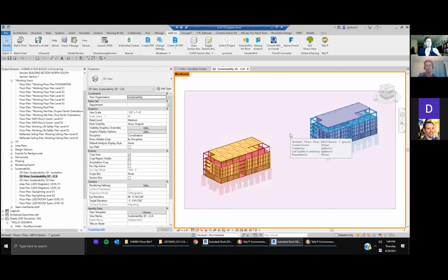This is totally detached. Because I'm going to work with work sets and I'm going to pull stuff away, I'm going to put all the toilets on a hide work set. I'm going to just clean all the work sets out to just get to what I'm looking at, which, for instance, if it's LEED compliance, we want cladding, we want the floors, we want the structure. So I'm going to work those into work sets in the ways that kind of make me happy. And dare I say it, if I am detached, there are times if I don't like something, I'm just going to delete it and get it out and bye-bye forever, which I try not to do, and I try to work through work sets. But sometimes life is life, and I don't need the furniture for landscape.